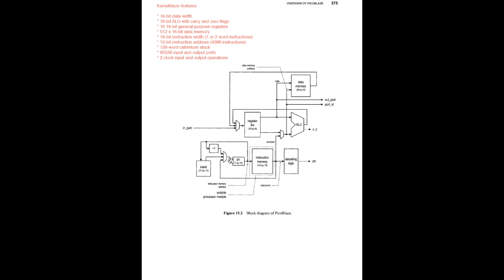In his architecture, he had one 18-bit instruction, which, recall, was an 8-bit architecture that allowed him to have one instruction per word. For myself, the implementation I chose is a 16-bit instruction. What that means is if I need immediate data, I'm going to need a second word to the instruction.